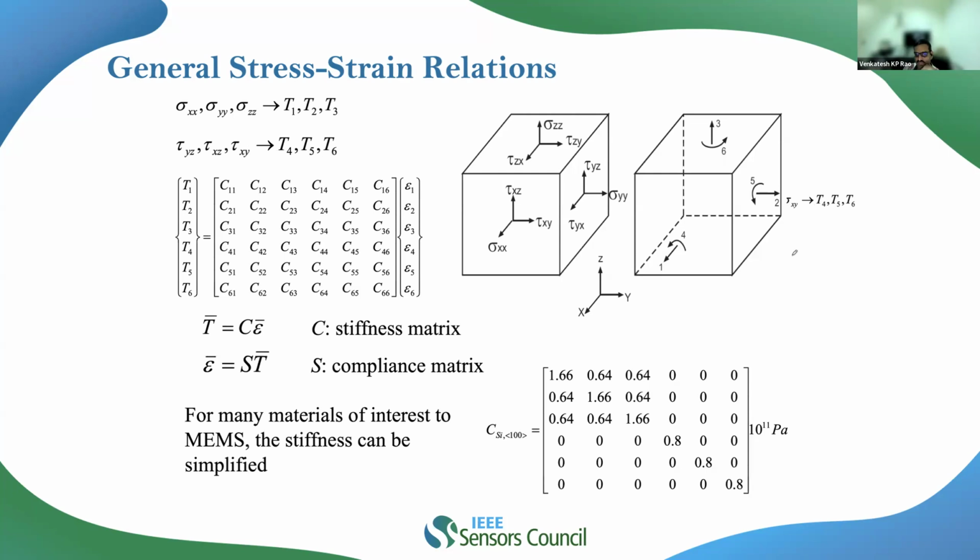Right, now whenever you take up a material and apply a load, what happens? There is not only elongation in this direction, at the same time there is a contraction in the other direction. So what does that mean? If I take a small element inside this, that element is experiencing stresses in this direction as well as stresses in the orthogonal directions, right?